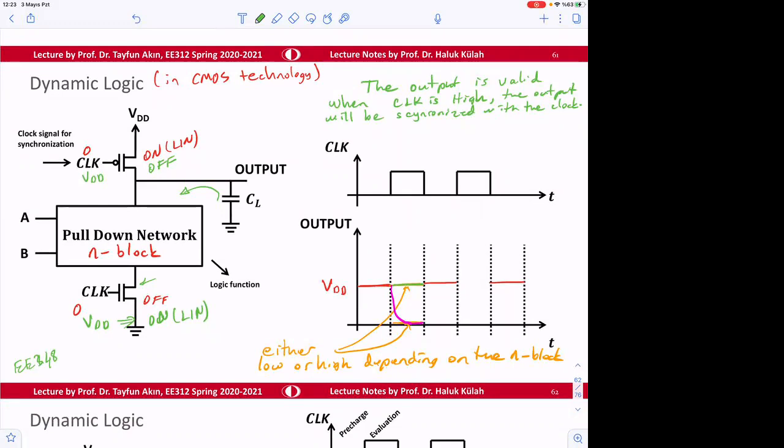So we need here 2 plus N transistors. Again, here, the output swing is from VDD to ground. So there is no issue in there. So minimum size transistors are okay, because the output is not constantly pulled up.